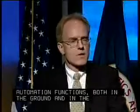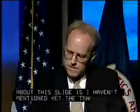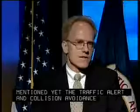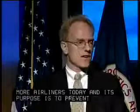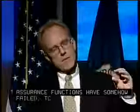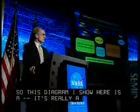One more point I want to make about this slide is that I haven't mentioned yet the traffic alert and collision avoidance system. The so-called TCAS system has been flying on most commercial airliners today, and its purpose is to prevent collisions in case all of the separation assurance functions have somehow failed. TCAS is there to prevent collisions. And so this diagram is really a layered system of separation assurance functions.